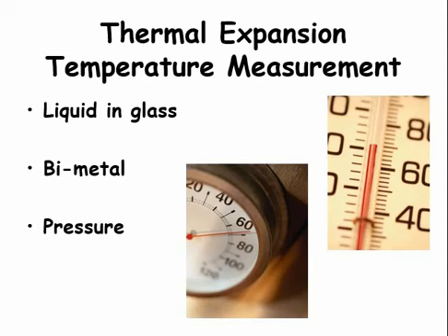Mercury used to be used in liquid in glass thermometers, but mercury spills from broken thermometers posed environmental and safety risks, so they were replaced with safer options. Liquids used can include pure ethanol, toluene, or kerosene, depending on manufacturer and working temperature range. Since these materials are transparent, the liquid is made more visible by the addition of a red or blue dye.